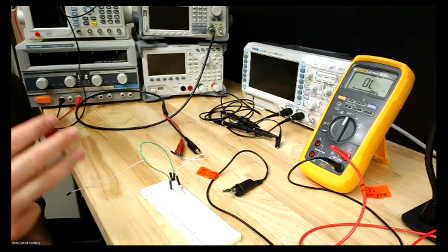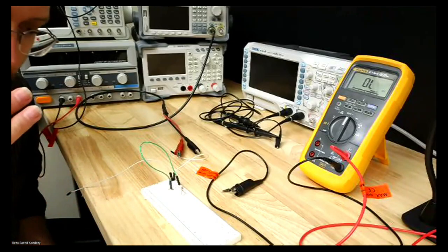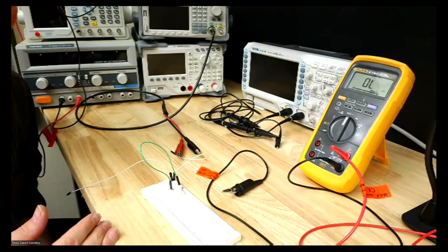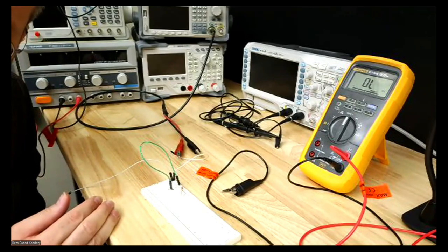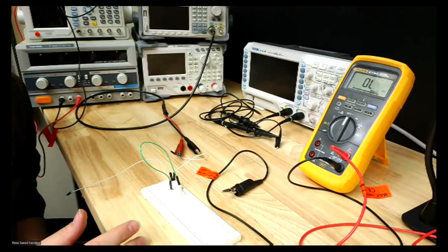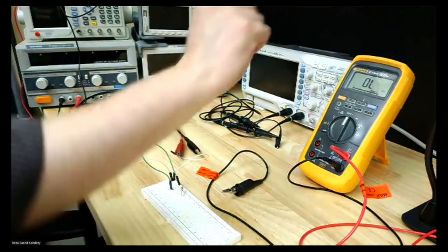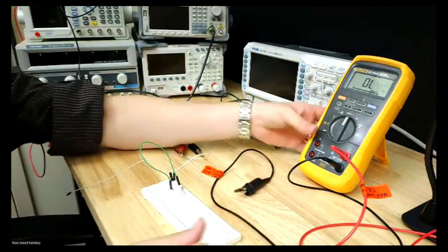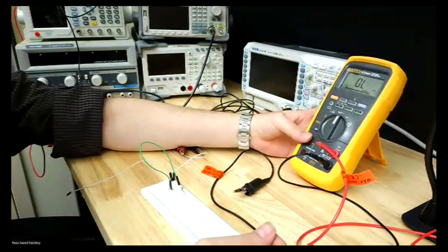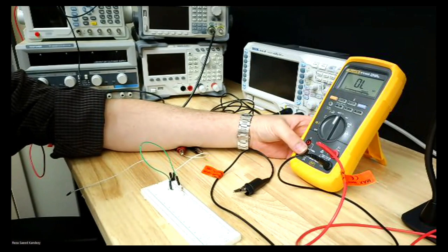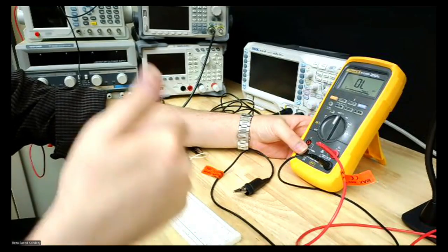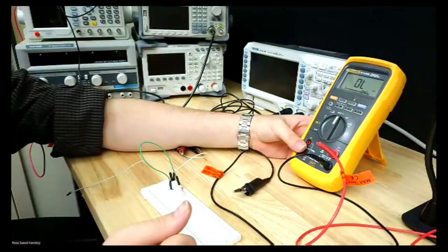And when you want to end the measurement, the first thing that you disconnect is also the source. Okay, that's a safety protocol. So remember that. Now, let's first measure the voltage across the diode, because we know that theoretically it should be 0.7. Our simulation showed 0.66. Now I want to see what the measurement tells me.